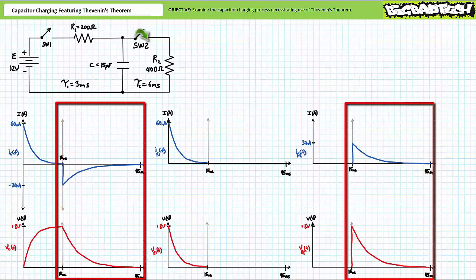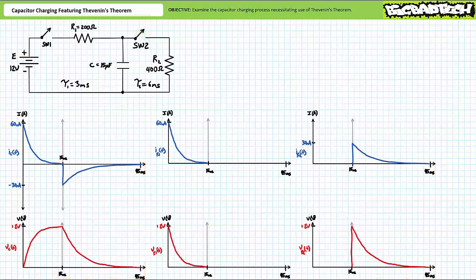When discharging, current rushes out of the capacitor and through a resistor. During the discharge process, voltage across the capacitor drops. Current out of the capacitor experiences an initial spike, which decays to zero after 5 time constants, at which time the capacitor is considered fully discharged. Any voltage experienced by any resistor during either the charge or discharge process is simply the consequence of the incoming and outgoing current experienced by the charging and discharging capacitor.